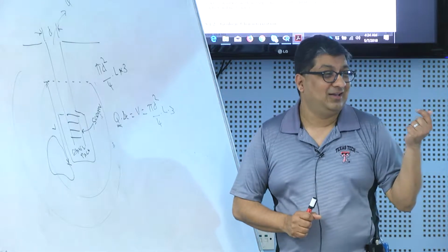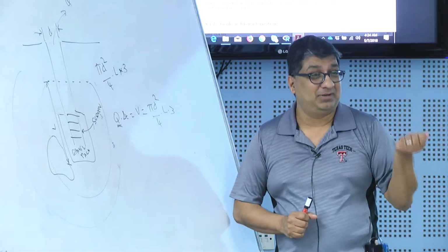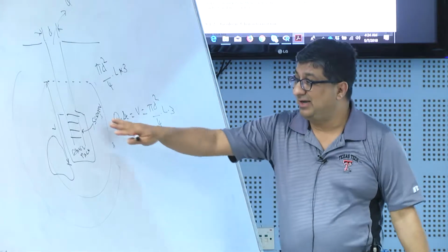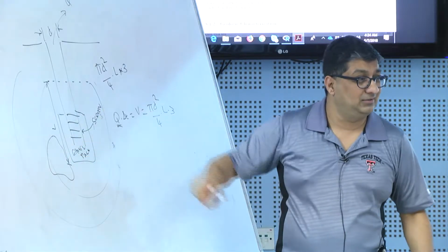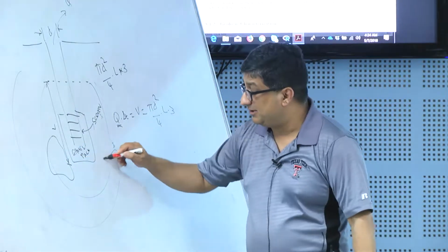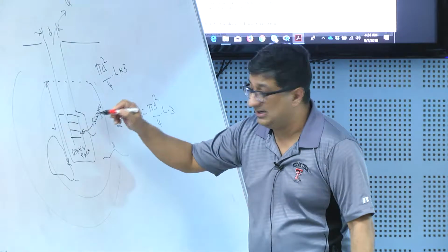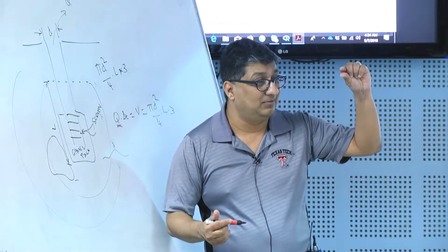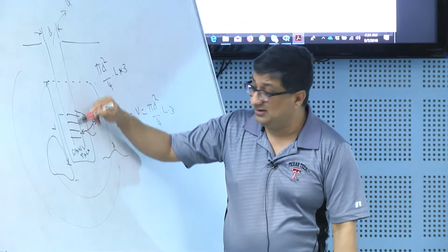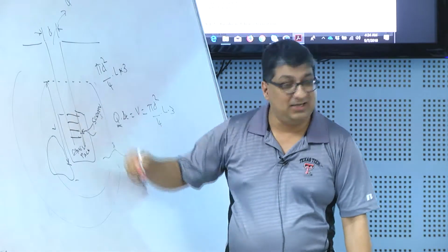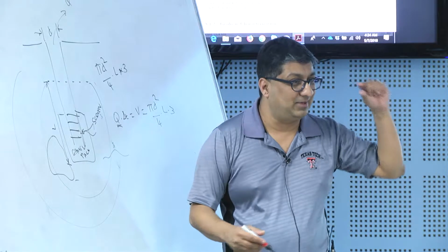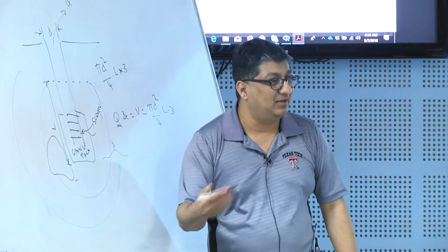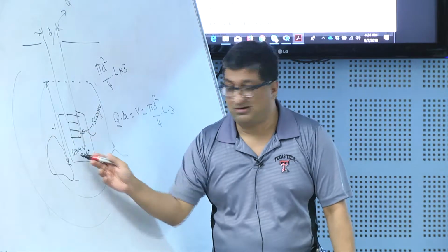We don't have to worry about being at the well too long. But the downside is if we pump at very high rates, we create turbulence right around this well. The water here is laminar, but when it hits the well screen, there is a very, very small opening. So overall the flow is Q, but over an individual piece the velocity is very, very high because the screen size is very, very small. Because your velocity is high, you get highly turbulent flow right around the well when you pump.